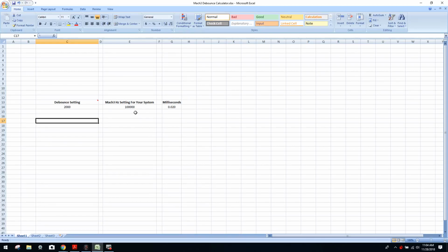If you're not doing CAD/CAM and just doing isolated Mach 3 use, I have some clients and potential clients who want an isolated computer. Again, I would still stay with the same processor. You could probably drop down to 4 gigs of DDR3 or DDR4 memory. That's up to you, but I would not substitute the Intel i5, i7, or AMD multi-core processors of today, or that memory. You still want the horsepower required to keep that system as stable as possible.